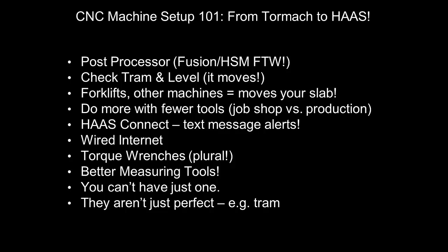Likewise, when you drive a forklift 5 feet in front of the machine, guess what? It moves. If you don't believe me, put a test indicator between your spindle and your table and drive your forklift 10 feet in front of your machine. It will deflect. It may not be a big deal, but it's something to be conscious of. When we pour our new slab, we'll probably do some isolation between our main slab and the machine slab.